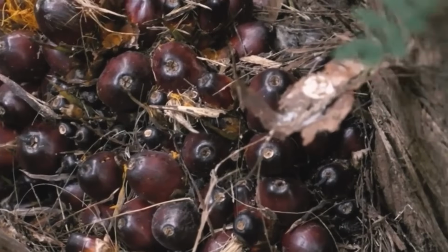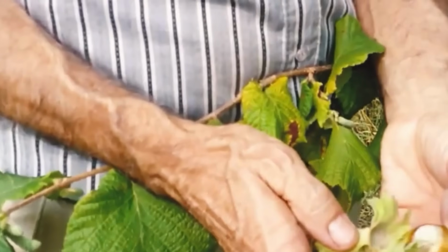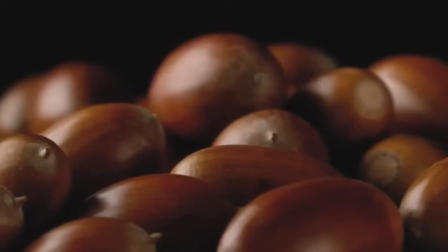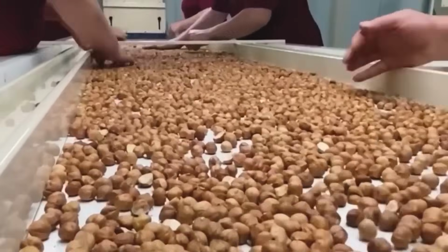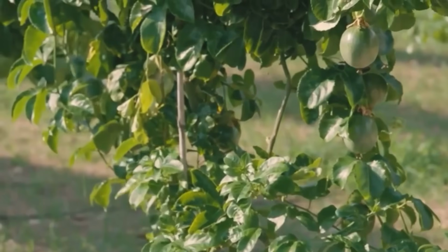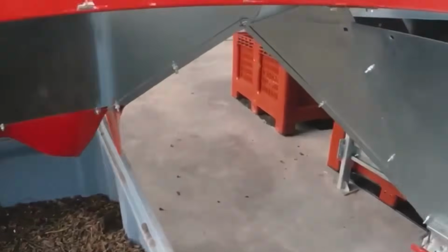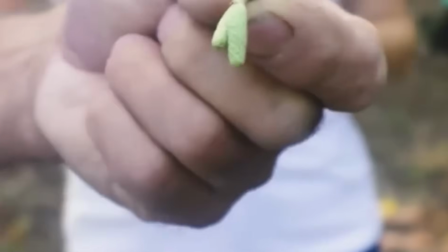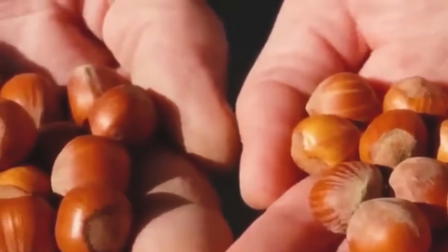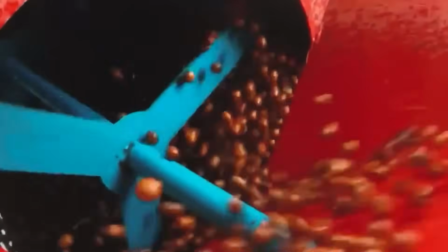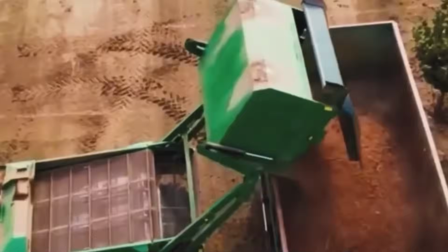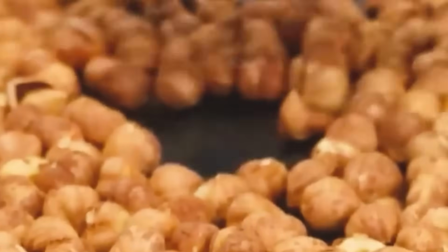This consists of a rotating die roller with cavity molds shaped to match the profile of the Nutella B-Ready shell. The dough is pressed into the molds using counter-rotating pressure rollers. An adjustable doctor blade removes excess dough from the roller surface. Molded wafers are transferred via a vacuum pickup system to a baking mesh conveyor, which passes through a tunnel oven with multiple independently controlled zones.